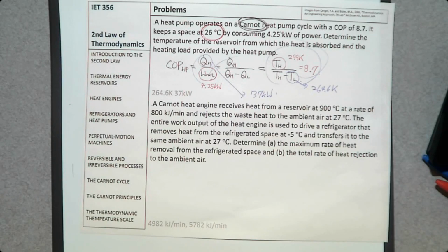So you can store energy in the form of heat. We usually use table salt, like a molten salt. You melt it, it becomes like water, but at an extremely high temperature, 600 degrees Celsius. You store that, and when the sun goes down, you use that heat to produce steam and then run the power plant. That is called CSP, different from PV.